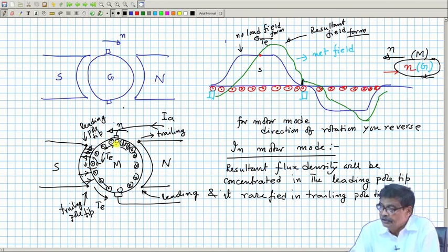What is commutation? The conductor has to cross this zone of the q axis where it feels that there is no induced voltage, no flux, but when the armature carries current, there is a flux, there will be induced voltage, there will be short circuiting current, and also it has to change the current from dot to cross in a very small interval of time.